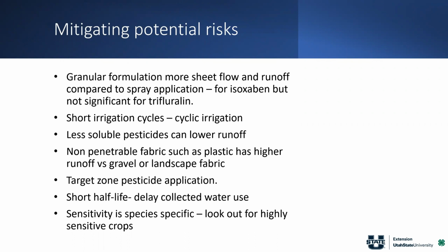So if the pesticide is not soluble, it will be less likely to run off and then be collected in the retention pond. Non-penetrable fabrics such as plastic, like the fabric that we use in nursery growing locations: if we have non-penetrable fabric, then the pesticide is less likely to adsorb and it moves on, and the concentration in the retention pond might be higher. Whereas if you have gravel or a landscape fabric, the pesticide can adsorb in there, and then the movement is lower.